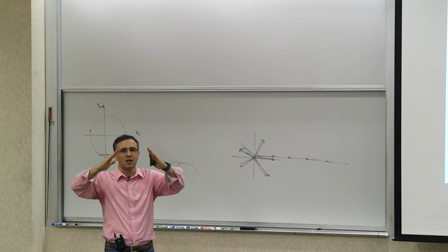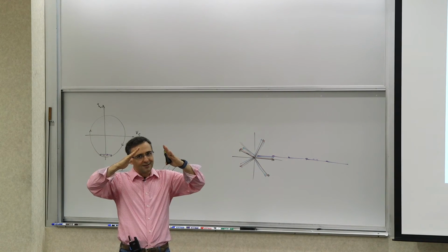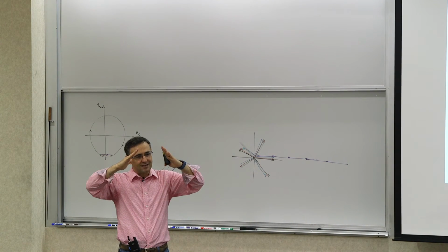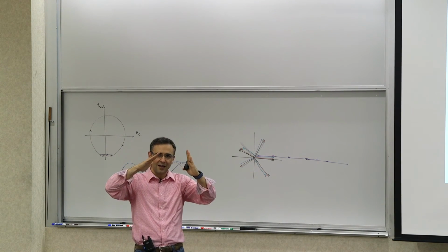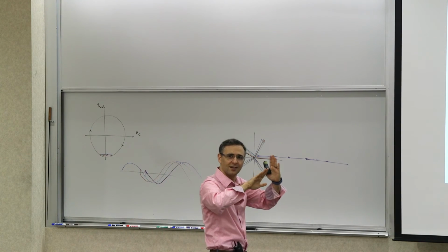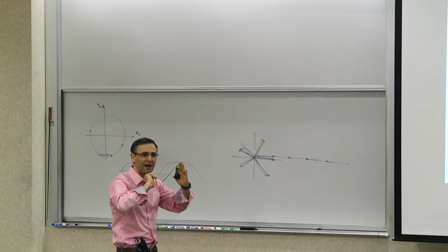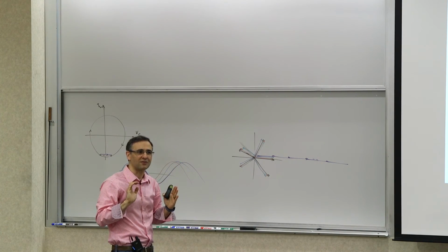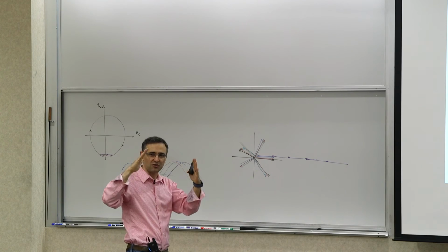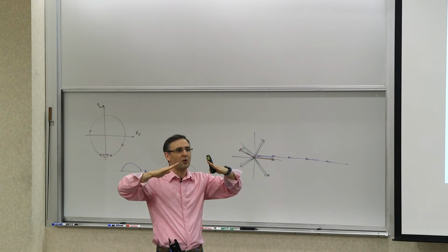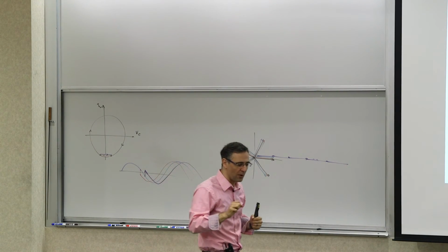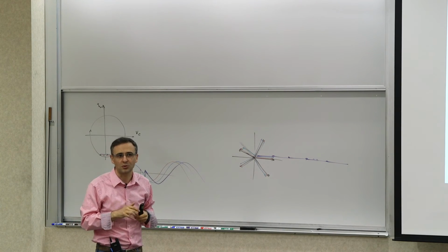Now, if the two transitions have the same slope, if you think about it simplistically, the total shift is going to be 0 afterward, right? But if one of them is steeper and one of them is shallower, what happens is that the amount I get shifted forward is more than the amount I get shifted back. So I will end up with a net shift. And this is another explanation for why the symmetry, the DC value of the ISF, plays a role. Because when the DC value of the ISF is 0, or the stage is symmetrical, the amount of forward shift and backward shift are going to cancel each other to first order.